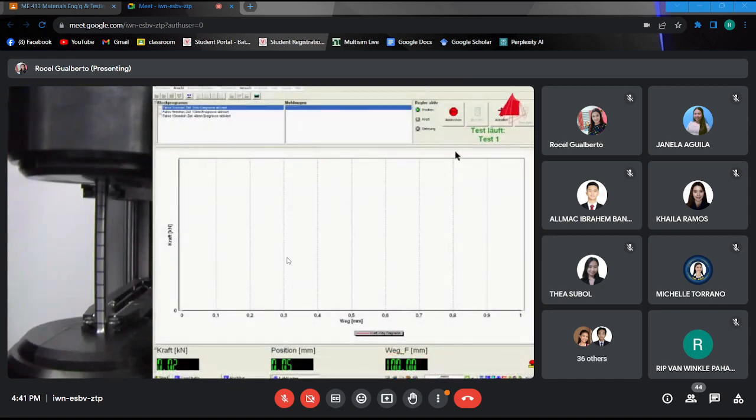During the tensile test, the test piece is slowly and constantly elongated with a standardized speed. The force that the test piece opposes to the imposed elongation is recorded and can be seen at the bottom left-hand force elongation diagram. The force F is being plotted upwards on the vertical axis, the elongation delta L towards the right on the horizontal axis. At first, the force rises rapidly.